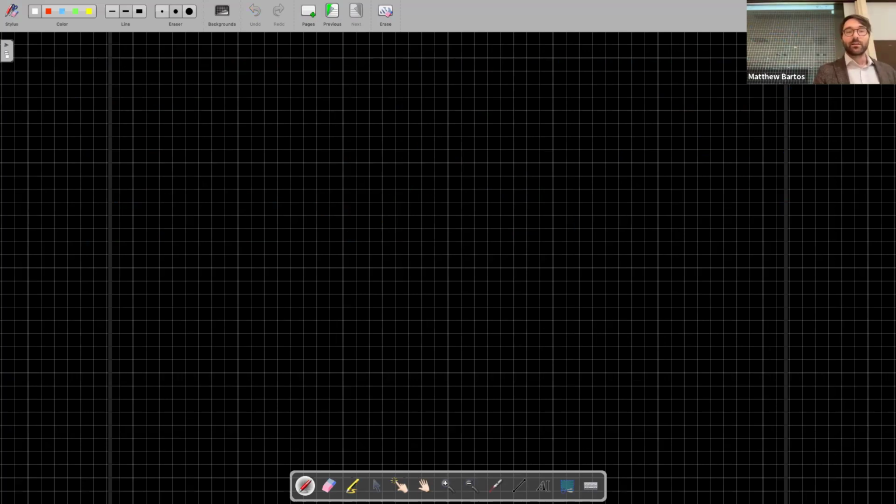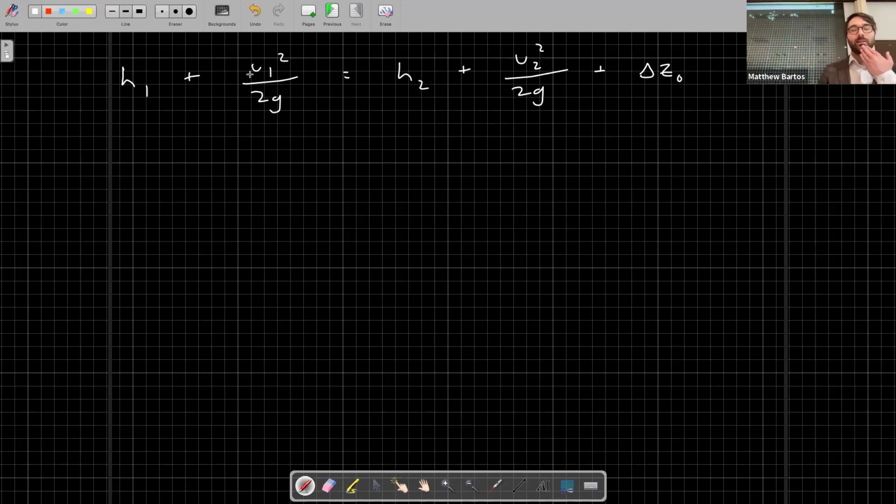So going back to our energy equation, we have H1 plus U1 squared over 2G is equal to H2 plus U2 squared over 2G plus delta Z naught. So we know H1, we know U1, we don't know H2, we know delta Z naught, and we don't know U2, but we know the discharge.